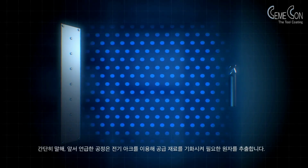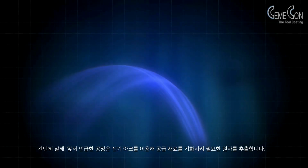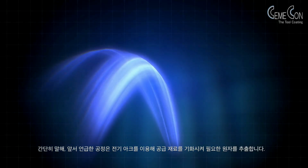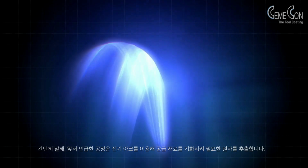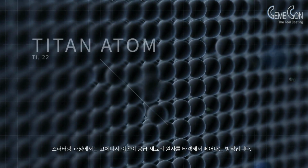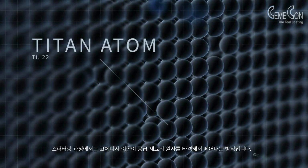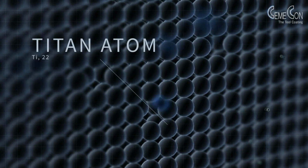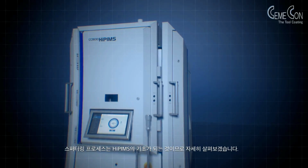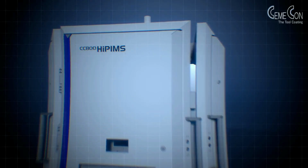In simplified terms, the former process uses an electric arc that vaporizes the donor material to extract the necessary atoms from it. In sputtering, the atoms of the donor material are removed by bombarding them with high-energy ions. Let's take a closer look at the sputtering process because it is the basis for HiPIMS.